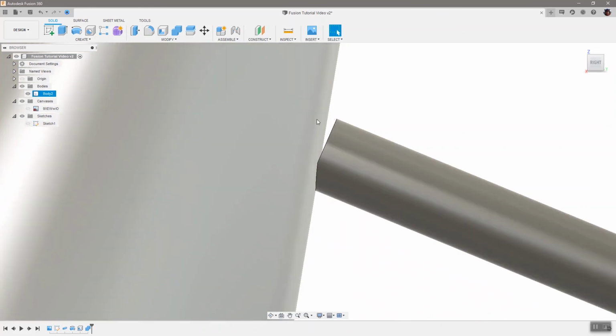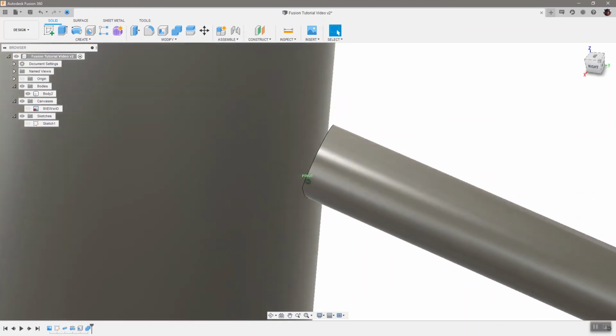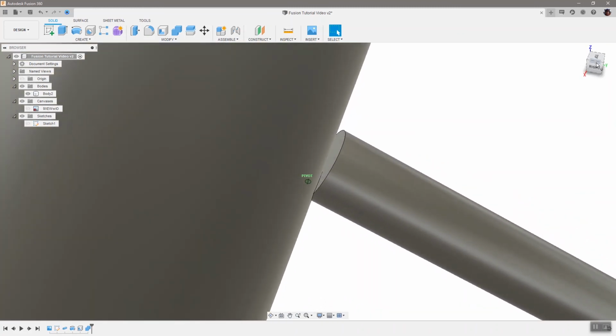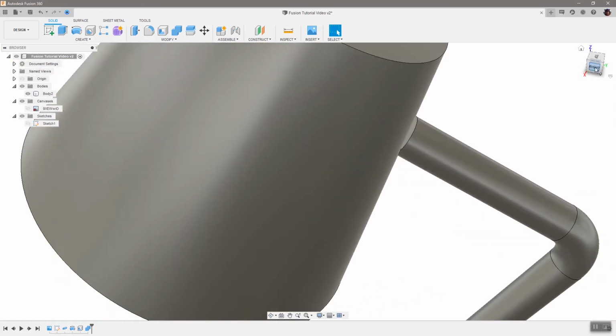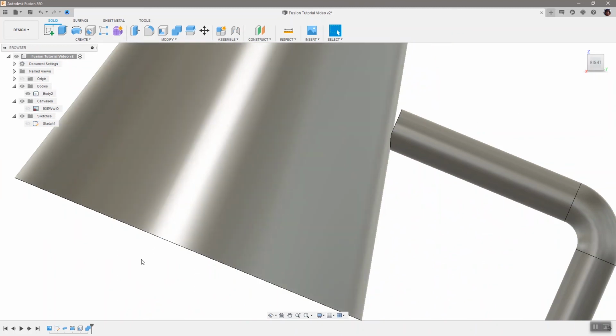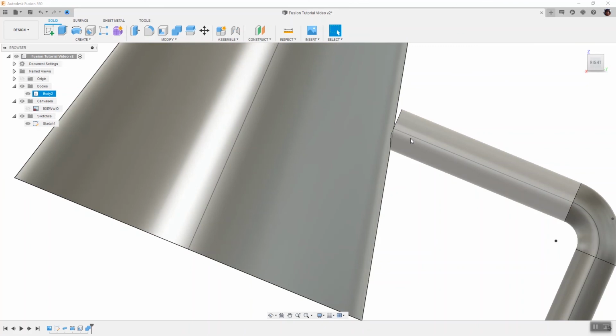Did you see this? This is a small gap. And these sort of things are sort of common for 3D CAD. This is not intentional. And if we look closely, I think we can all understand where this came from. We created a pipe that was based on this sketch. That sketch line that was the path for the pipe only went to this point here.